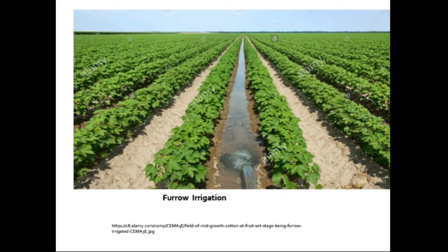The advantages of the furrow irrigation method are that there are low evaporation losses as only one half of the irrigated land surface is wetted. Likewise, it is possible to cultivate earlier in heavy soils. Furthermore, furrows serve as drainage ways for surface runoff in areas of heavy rainfall, and are especially suitable for crops like maize that are injured by contact with water.